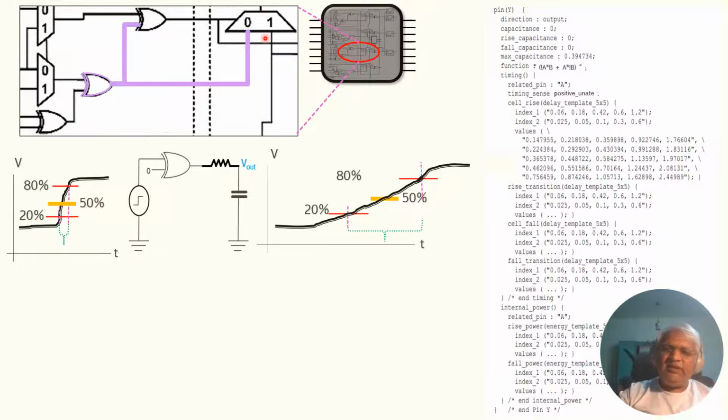So it will take those calls and finally improve the incoming transition time for this cell. Similarly, for this cell, the incoming transition time, that is the output transition of the previous cell, finally ends up better and falls within this table, the index 1 line of the cell we are talking about.